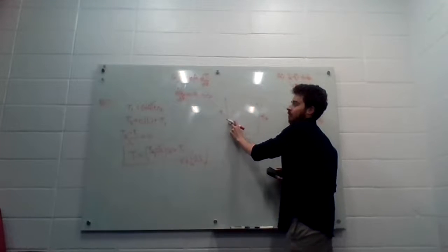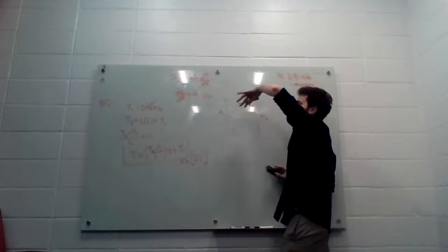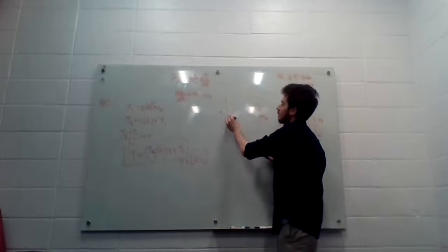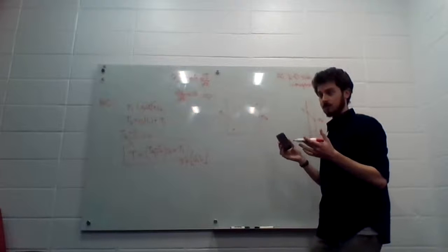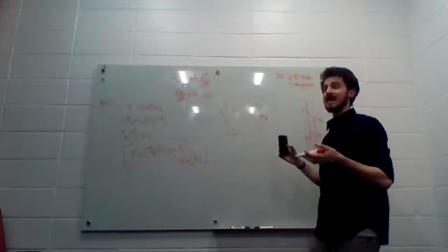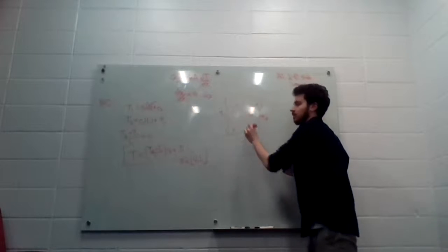So if you've got a wall that's hot over here, and a wall that's cooler over here, we're going to assume this thing is very tall. If there's not that many particles to transfer energy, that kind of thing would determine the thermal conductivity of the gas. When you've got more particles, you've got more energy carriers.